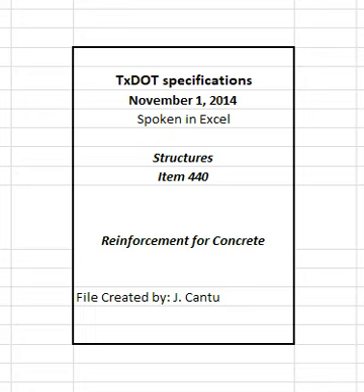Contact the Construction Division with the name and location of the producing mill for stainless reinforcing steel, low carbon/chromium reinforcing steel, or dual-coated reinforcing steel at least 4 weeks before ordering any material. 2.2 Deformed steel bar reinforcement. Provide deformed reinforcing steel conforming to one of the following: ASTM A615, grade 60, 75, or 80.